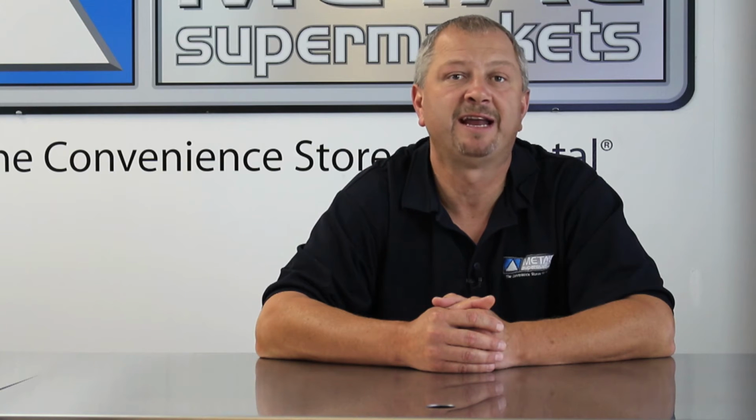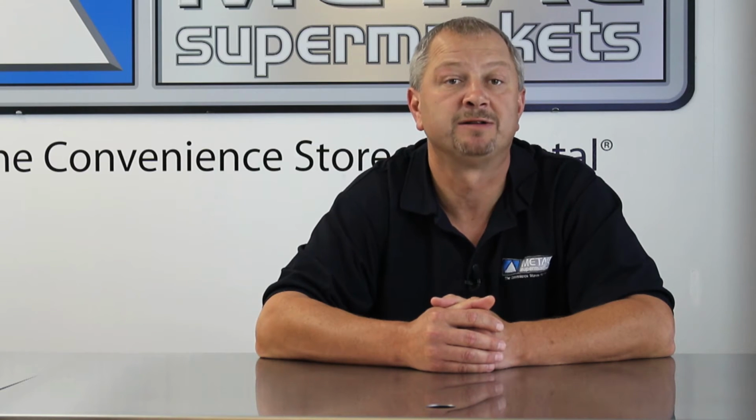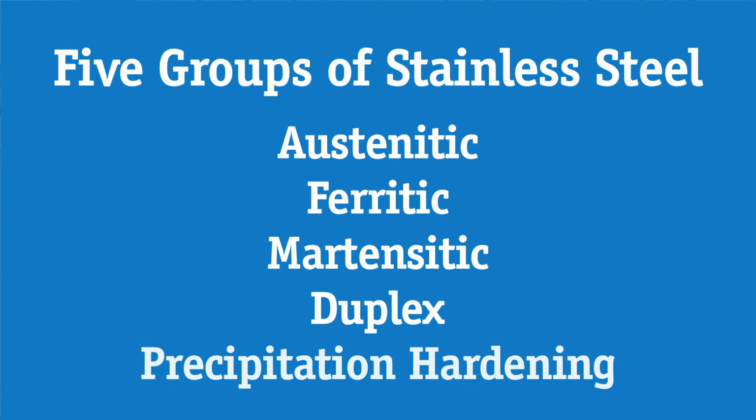Stainless steel typically contains between 10 and 20% chromium. It is the main alloying element and helps to make stainless steel extremely corrosion resistant. In fact, stainless steel is about 200 times more resistant to corrosion than mild steel. Stainless steel can be divided into 5 groups: austenitic, ferritic, martensitic, duplex, and precipitation hardening.